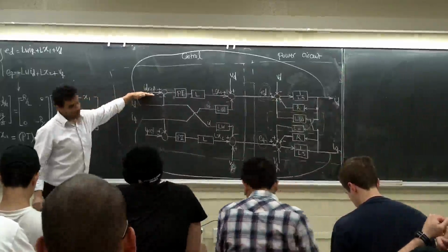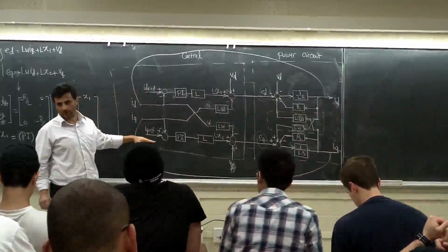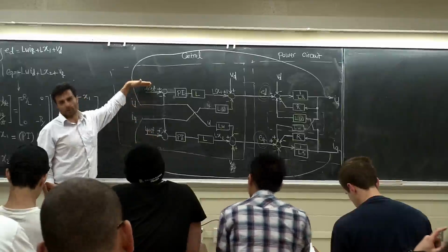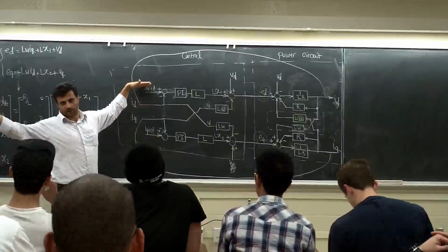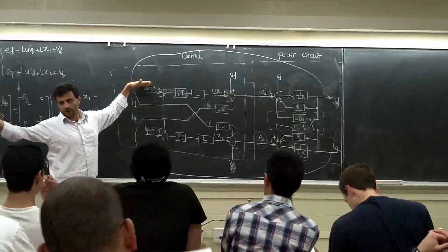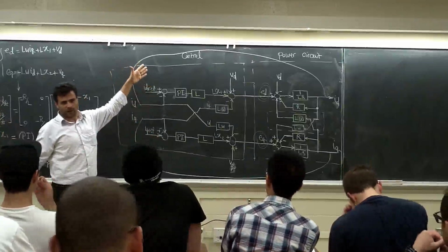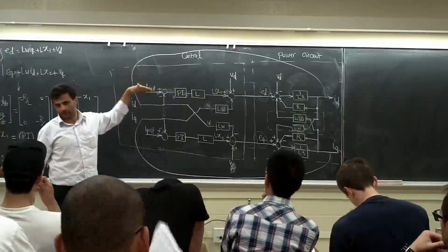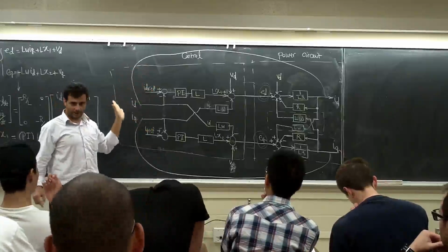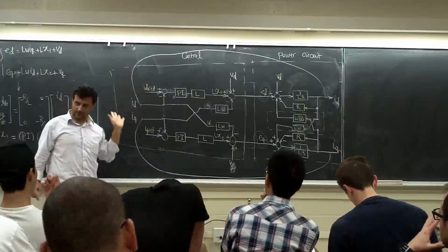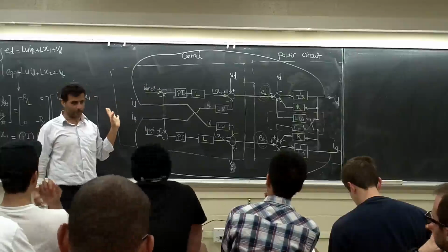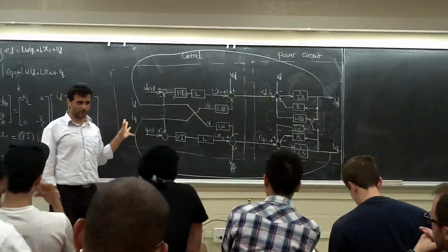I wanted this much ID ref, I want this much IQ ref, right? Basically, it means how much P I want, how much Q I want, right? Like the previous block diagram I drew out, we said we should divide it by 2/3 V, something like that. We calculate that one, right? If you have a P ref and Q ref, does anything ring in your mind, what I'm saying? Have a look at the previous block diagram we had for the DQ control.